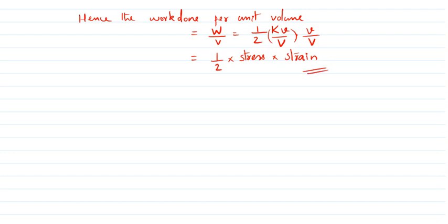This equation we also already got in longitudinal strain. So work done per unit volume will be half into stress into strain. Now we will discuss what is the work done in the case of shearing strain.